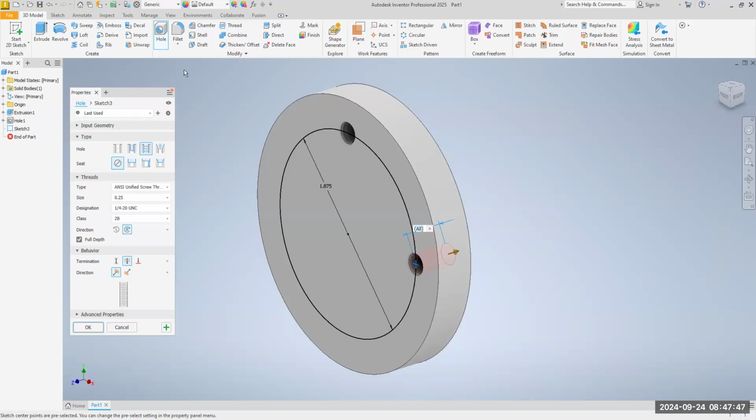If you look at the call out on the drawing, it says the diameter that goes all the way through is 0.27 to give clearance for a 1/4 inch screw. And the major diameter, the larger diameter part, the conical part, if you will, has a diameter of 0.51 and an angle of 82 degrees. Here's how you create this.